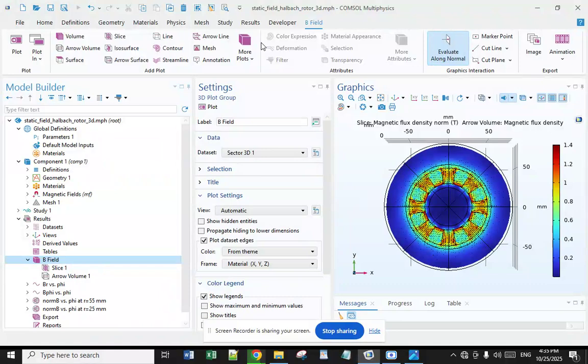Cylindrical Halbach arrays are used in portable MRI scanners. They offer the potential for a relatively lightweight, low to mid-field system with no cryogenic electromagnetics, a small fringe field, and no electrical power requirements or heat dissipation needs. The reduced fringe fields also enhance safety and minimize interference with surrounding electronic devices.